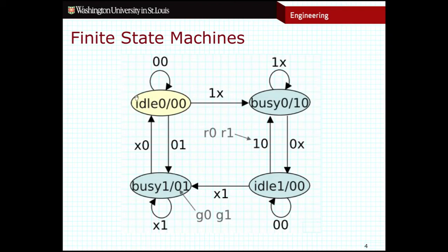Sometimes you might see an arrow pointing to the starting state instead, right? So if you see an arrow pointing to the starting state or a lightly colored state, that is our initial state. That is where we begin, right? The arrows dictate transitions. So remember that transitioning from one state to the next depends on where I currently am, as well as what my input values are. So along with every single transition, I see a set of inputs.